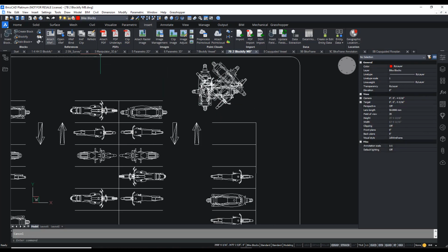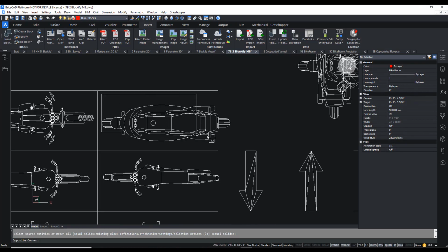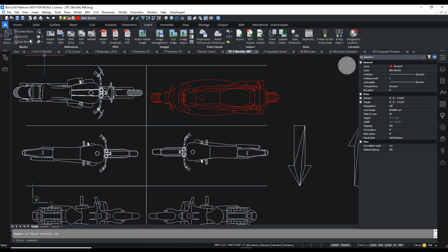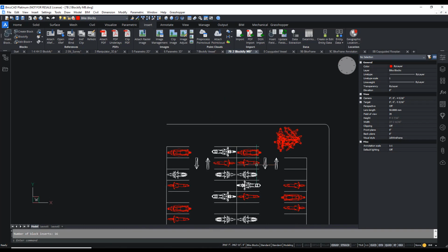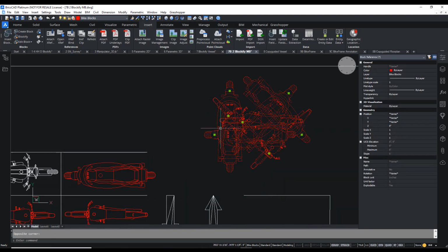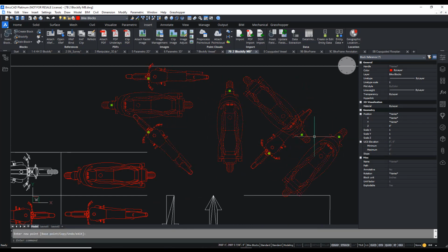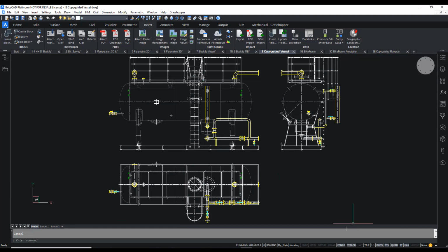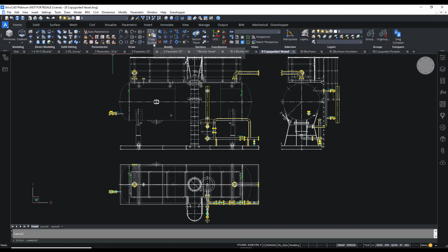Now, in our second example, you can see that we've got quite a mess of exploded geometry. Multiple motorbikes were copied, rotated, and unfortunately exploded. In seconds, Blockify converts the geometry into existing block definitions with all the correct colors, layers, and properties automatically applied. Without Blockify, you'd probably just erase all of this and start from scratch. Blockify is the most efficient and effective way to reduce drawing size simply and easily. In fact, you can reduce DWG file size up to 90% with the BricsCAD Blockify workflow.